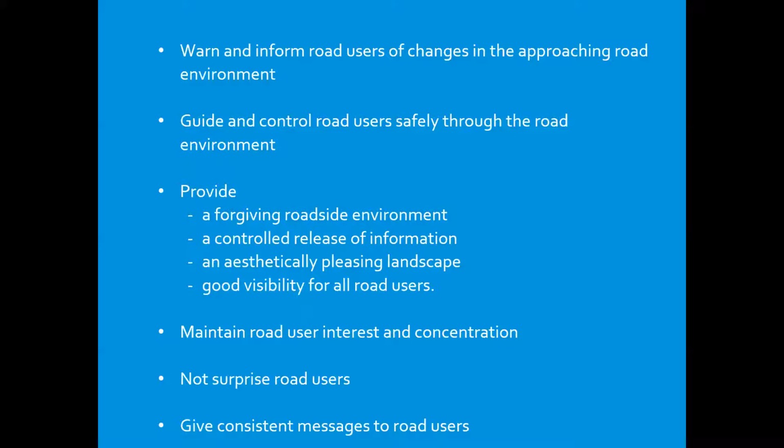The effect of road design is somewhat obscured by the presence of these factors, and most accidents result from a combination of factors interacting in a way that prevents a single factor being identified as the cause of a crash. However, even when a vehicle leaves the road due to driver error or mechanical failure, good roadside design can mitigate the severity of crashes.